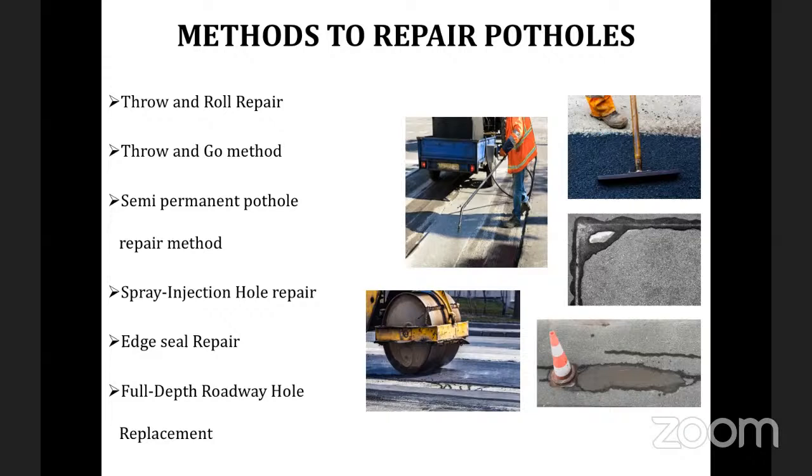Next one is the throw and go method. This is one of the common methods they usually use, BBMP officials also do this type of thing. Here what they will do, they will take the material, quickly apply it, and go off. They will not roll it, they'll just throw it. They will just use the hand compactor to compact it. Here we can see the one with the shovel. They will just put it, compact it with the hand tool, and go off.